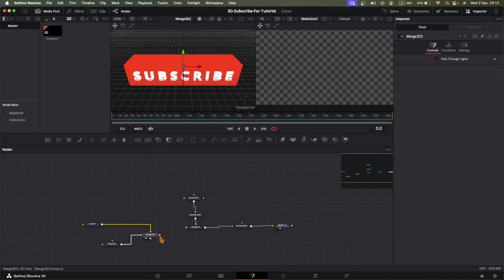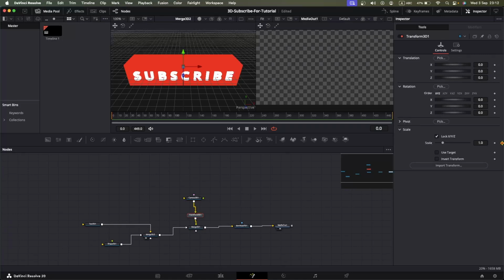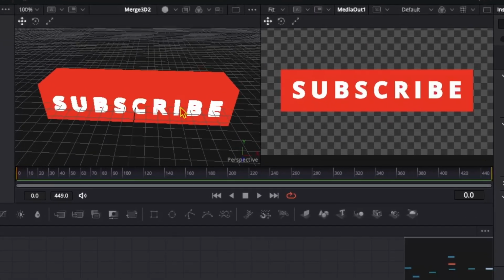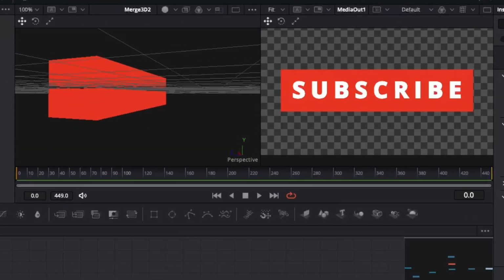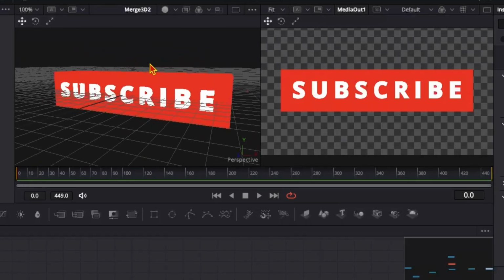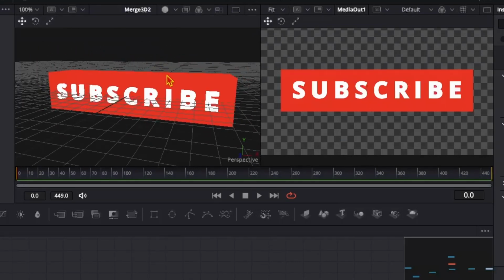Now link this merge 3D node to the other merge 3D node so that everything is connected, and go to the transform 3D node of the camera and just change the translation to 3.9. And now we can see everything in the right screen as well. But for now, we have only the subscribe text in front of the shape 3D node. We want to add it on all of the faces of the shape 3D.